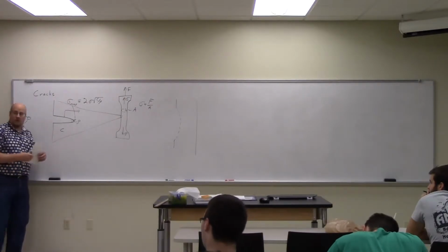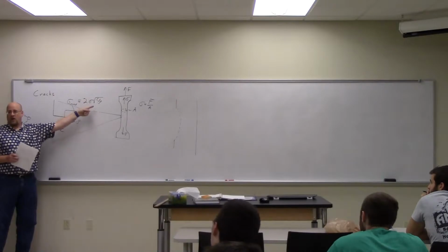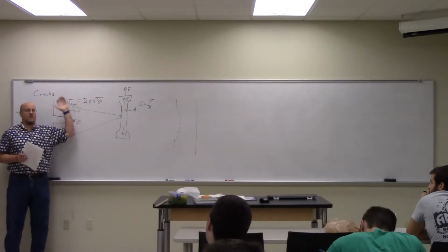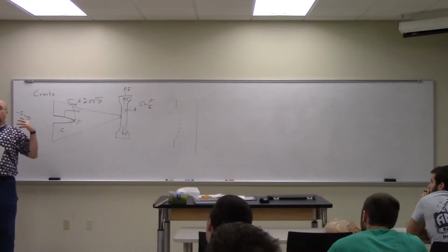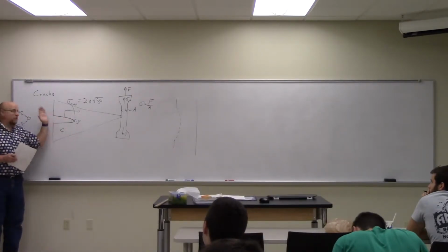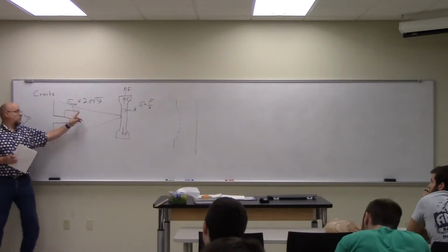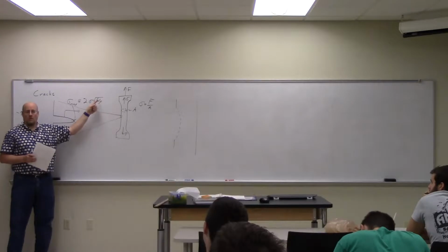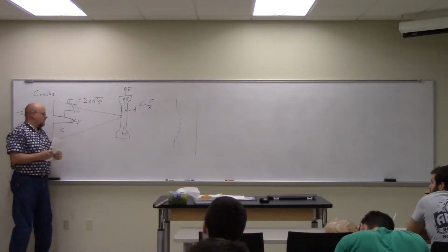Anyway, all right, so does everybody get this? C is longer than rho, so C is a lot longer. If it's an atomically sharp crack, you have huge concentrations of stress. So if you want to relieve the stress and keep the thing from propagating, you either have to polish away the crack, so we get C small, or you have to blunt the crack.